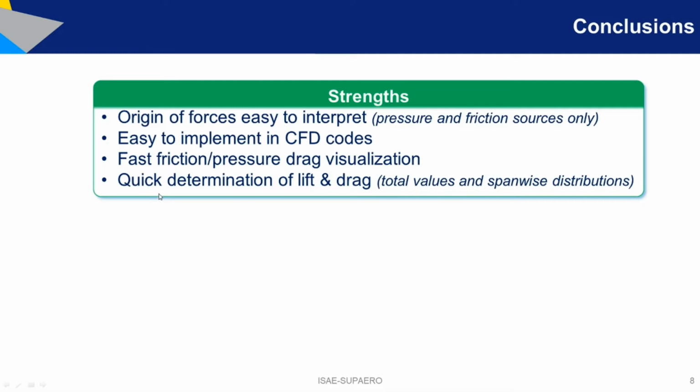The other advantage of this method is that it allows you to determine lift and drag in a very fast manner, for both approaches, the total values of lift and drag as well as the span-wise distributions. So as I mentioned before, the near-field method is quite practical. It gives you a good starting point to perform further detailed, physical and meaningful analysis by other methods.